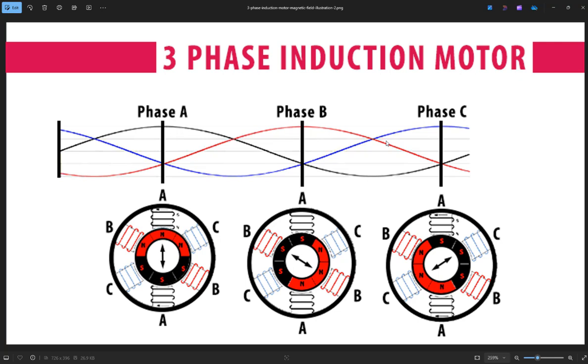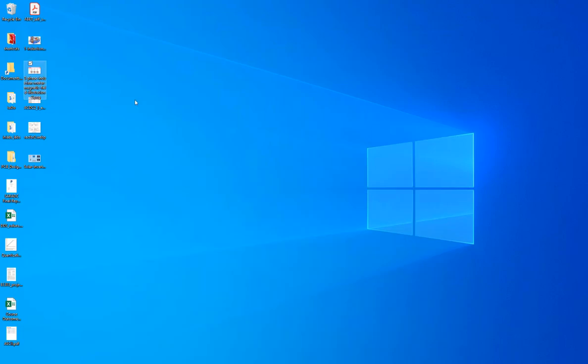Okay, whenever you have a heavy load, for example a shopping mall or factory, which have a lot of appliances or equipment requiring high power, you need a three-phase power supply. But in your house, usually what drives your fridge and other things is just one-phase AC, 110. So these are not three-phase power supplies. Okay, just some general big picture about why we care about AC voltage in three phases and induction motors.